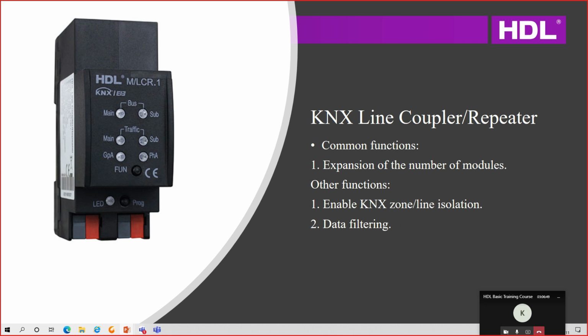And we also have KNX line coupler or repeater you may be more familiar with. Its common functions is it can do the expansion of the number of modules, and this function is similar to the IP router, and it also has other functions, like it can enable KNX zone line isolation and also can do data filtering.